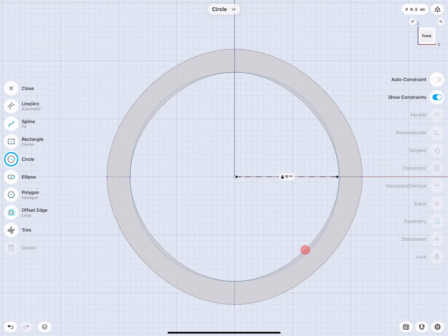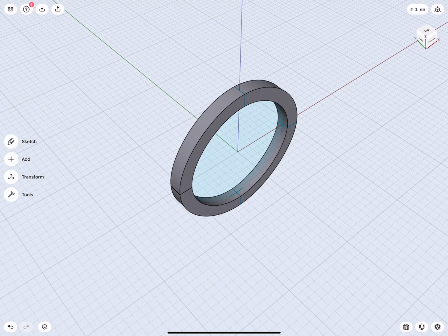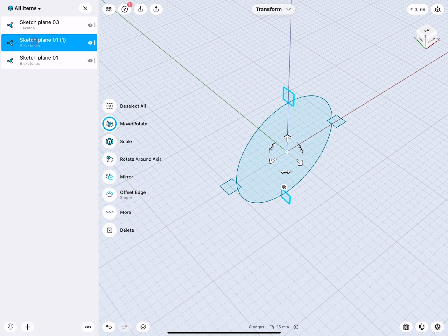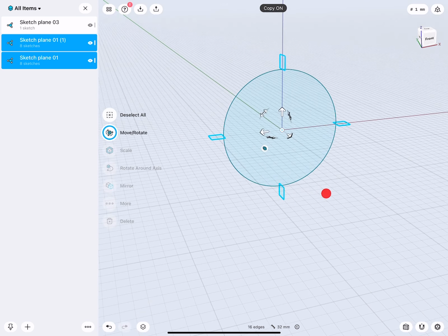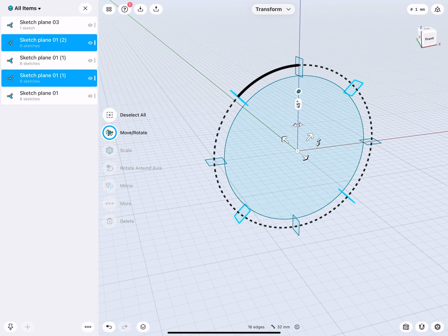And now you can really see the problem. So the loft is just lofting between these sections, and to make this look more like a circle, like a revolve, we need to have sections there too. Now this is actually very easy to do. All we need is we go to the overview, select the 2 sketches with the 4 rectangles, turn on copy, and then we add 45-degree rotation copies.